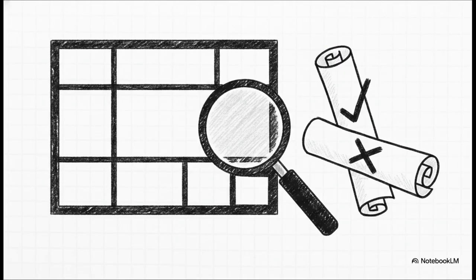Before you go walking the boundaries, take a second and look down at the bottom corner of your plan. The title block is basically the ID card for your specific project. It's got the project title, the scale, north point, date, drawing number, and the revision number. Actually, scratch that. Pay special attention to the revision number. Plans change constantly, right? Checking this guarantees you aren't accidentally building off an outdated roadmap.